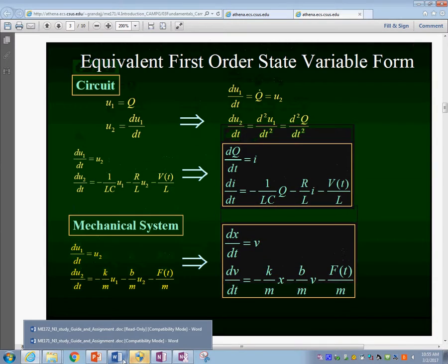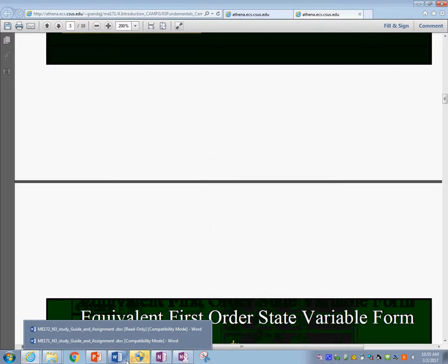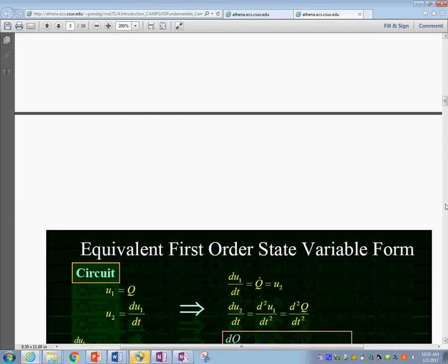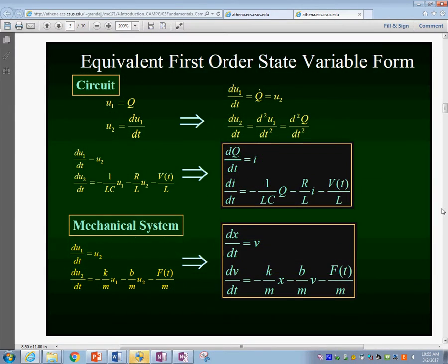From those equations, you could transform them into first order and get a state space form. Or you could directly describe these equations to Simulink, using double integration, and then you get the result. Or like I said, you reduce them to first order like you see over here.